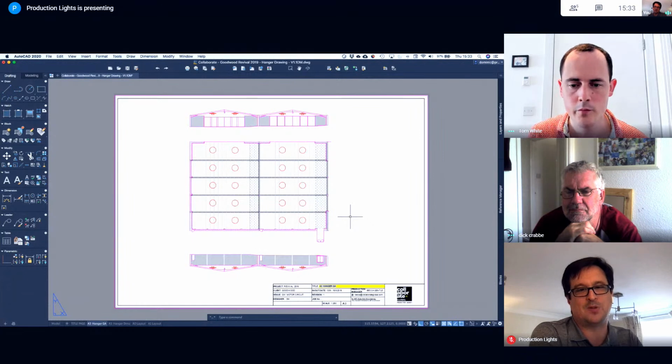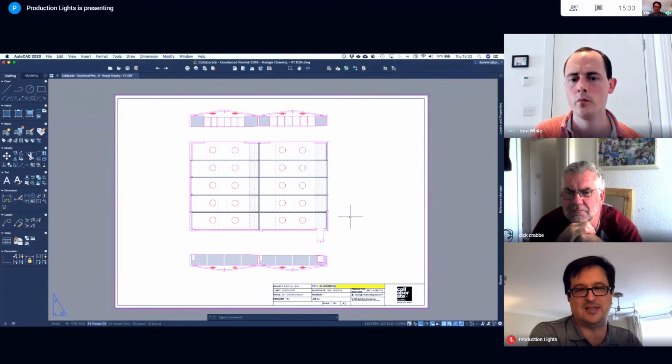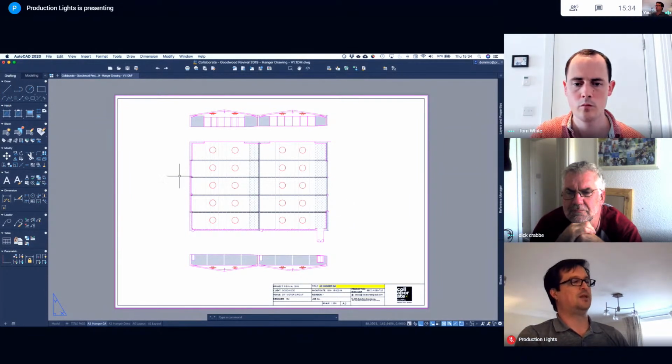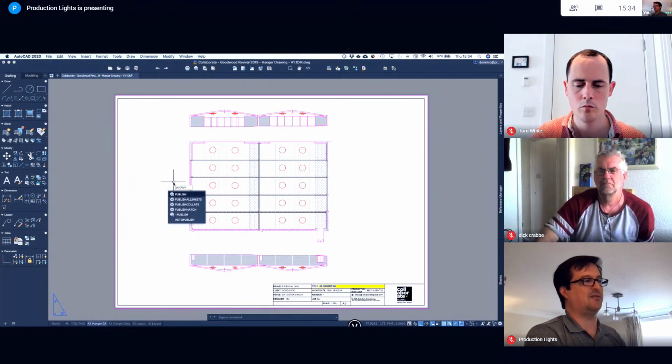If somebody sent you, as Tom showed last week, a PDF of a venue, and you just want to get it in, get some lines out, click on the layout at the bottom, put the viewport in the right place and hit publish. Being able to hit publish without having to come and edit stuff is pretty crucial. So we've got those set up. You're happy with your layouts because it's your template file.